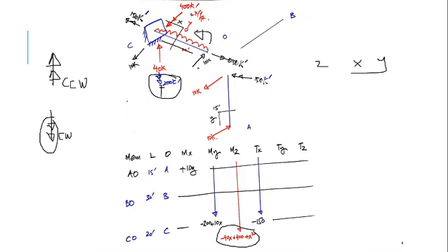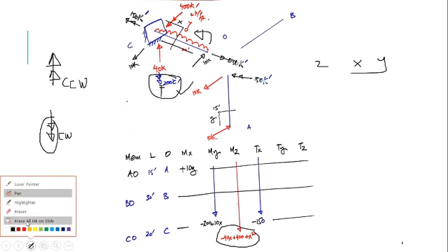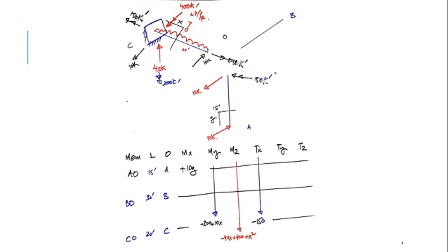The moment due to this 10 kip foot load has been mentioned here, and this load has been balanced as well. Next we have this UDL, because this UDL can form a moment as well. For example, this UDL 2 kip foot is in Y direction because it is acting downwards from Y, and this member is in X direction. So there would be a moment in Z direction.